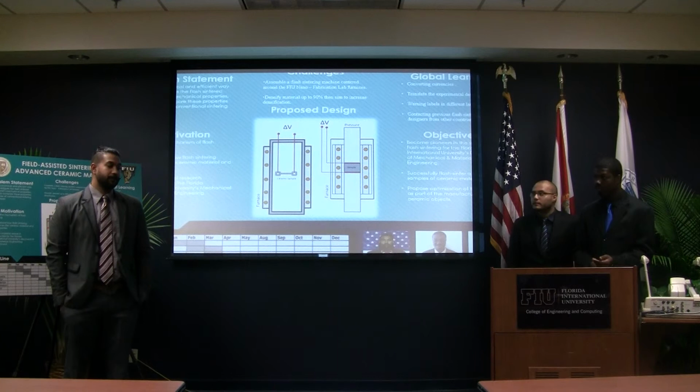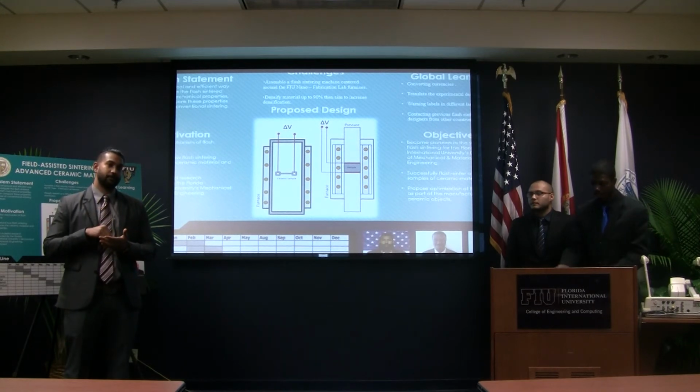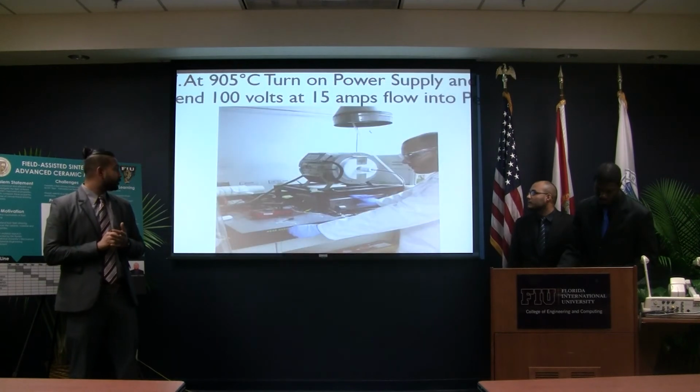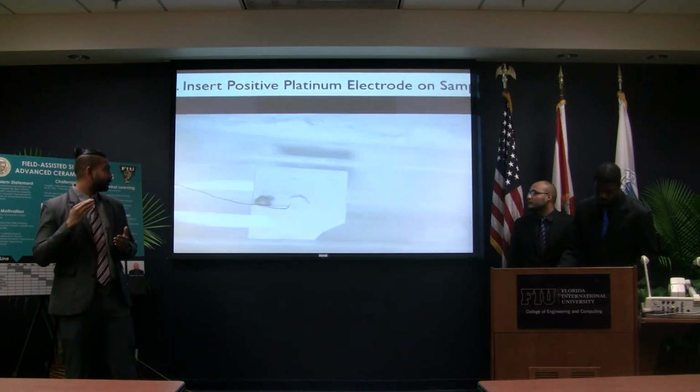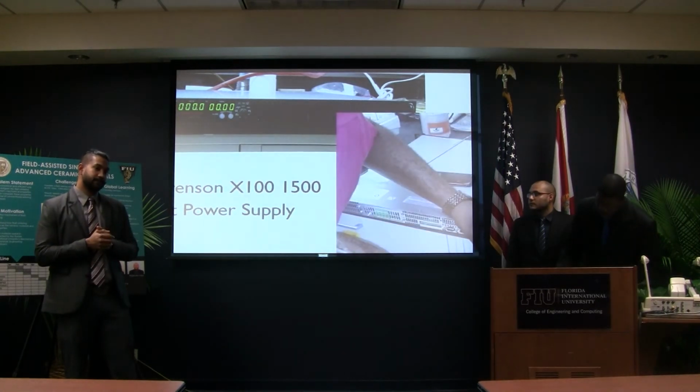Yeah, the reason that we chose the dog bone shaped die is that the shape is supposed to allow the current to travel more evenly throughout the entire sample. And with our power supply, we could set exactly how much voltage and what wattage we need. So the hope was that using that die would get it to sinter successfully, with the current flowing evenly through the sample.